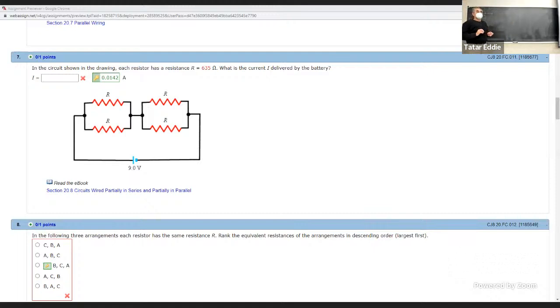Didn't you say that if the voltage is the same, then the 2 resistors are? Yeah, well, look, you're right. But if I had different values for the resistances, the voltage wouldn't be the same. So say, for example, you have 255 in that top left one, and then you've got 250 in that bottom right one, they're no longer in parallel.